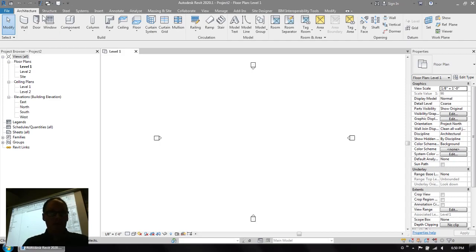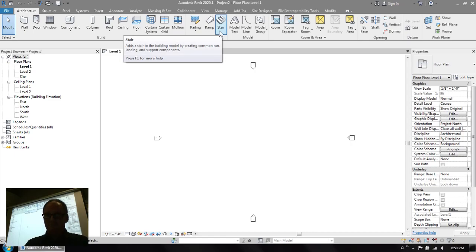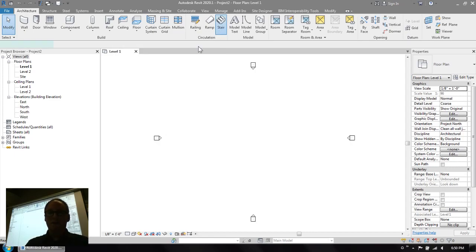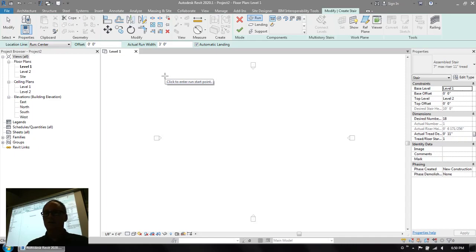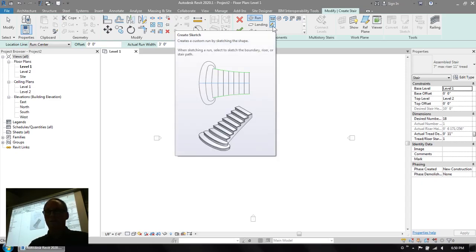Okay, so in the Stair Tool set, when you start up the Stair Tool set, you are able to go into two different creation modes for building stairs. Now, it's not really obvious, but this button here allows you to go into sort of the old school Revit stair mode where you're using green lines for the edges of the stairs and black lines to draw the risers. So those are your two different options.